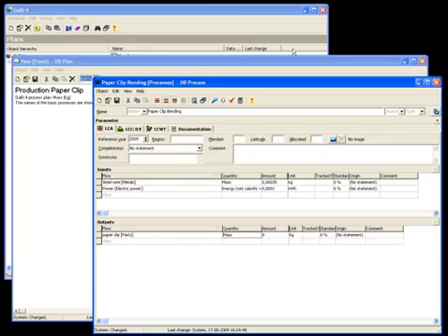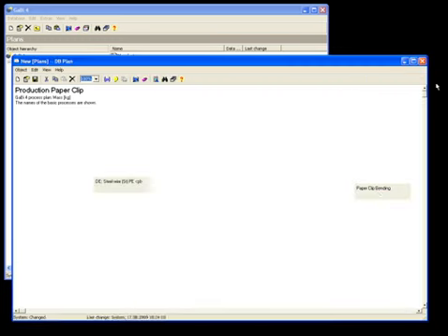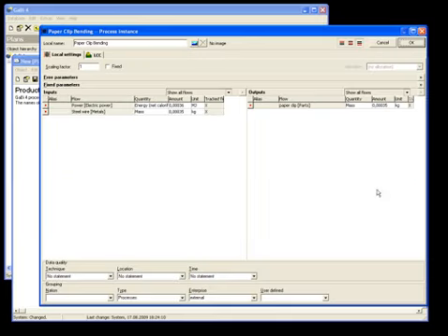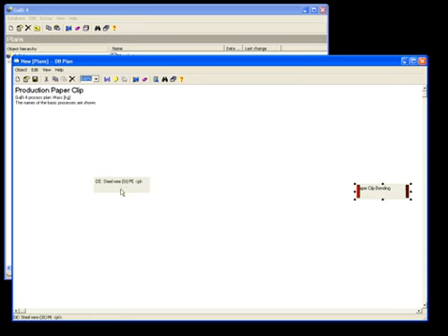In order to connect processes together, the connecting flows have to be tracked by marking with an X. By double-clicking on the process, its properties can be displayed. Here, the process can be scaled. For example, scaling to 1000, the input and output amounts will update automatically. When the scaling factor of one process is fixed, all connected processes will scale automatically to the amounts of the fixed process.